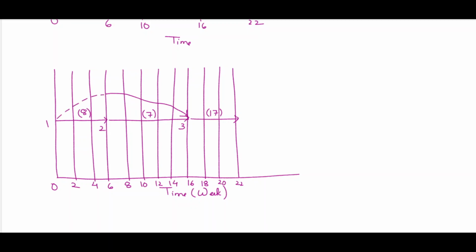So we have not changed the duration of anything, we have just rearranged the whole timing. It is a general notion to start from the beginning. That notion we have just changed as per the requirement of the problem. We want to reduce it to 17 because resource leveling means it should be leveled. All manpower requirements should be leveled. As in two boxes we got 17, 17, we want to reduce the first one and increase the third one. So now its manpower requirement is 4.